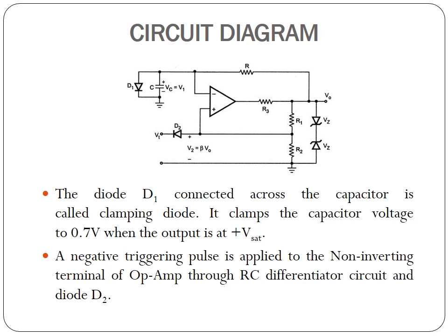Next, select values of R1 and R2 such that the voltage at the non-inverting terminal is greater than 0.7 volt. So output is positive saturation voltage. The voltage across the capacitor is always 0.7 volt because of the diode. In forward biased condition, the resistance of the diode is very small. So the capacitor is almost short. So no charging takes place.